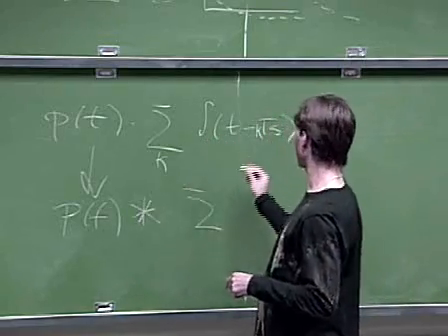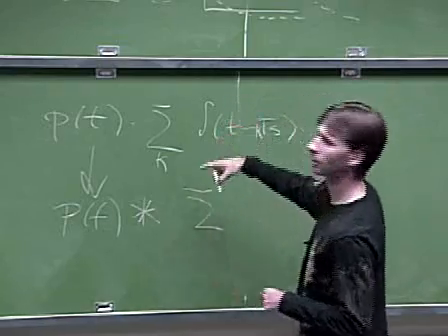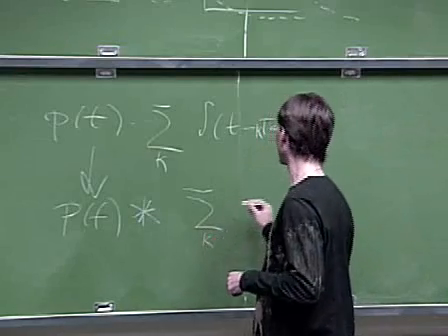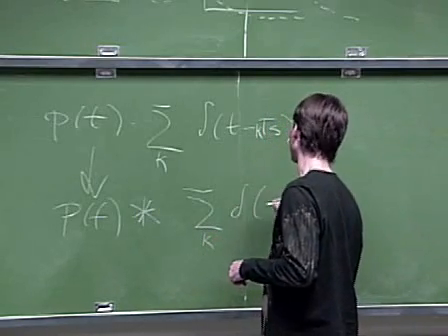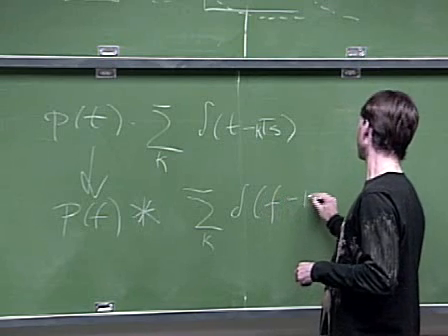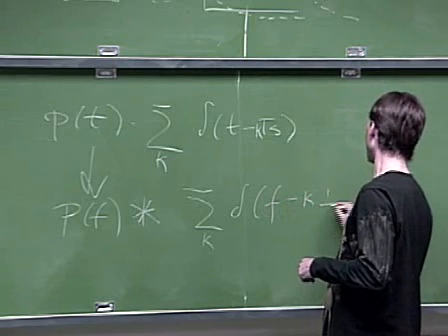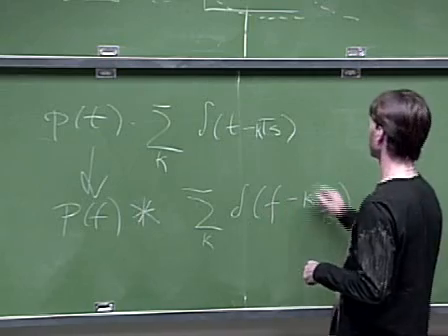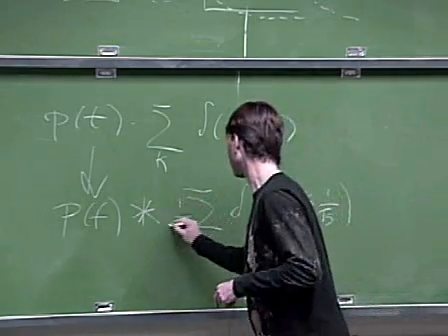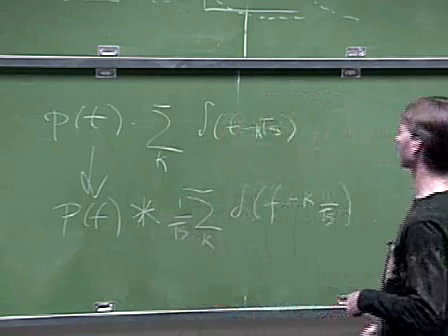It's actually pretty easy to prove. You can just use the definition of the Fourier transformation and do the integral. And you get another train of impulses, this time in frequency, spaced by 1 over T_s, which is the reciprocal. And there's a scaling factor outside of 1 over T_s.